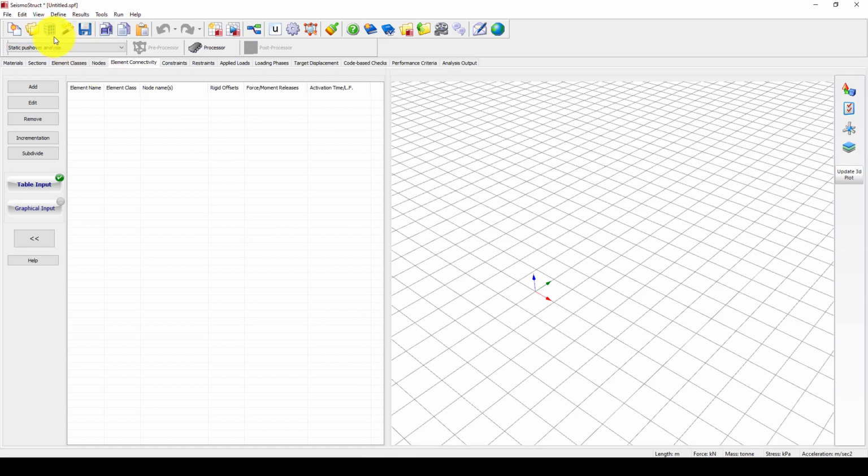So in the last part, you can go to the global response parameters, and you can check specific columns, beams, everything, and you can see the displacement and rotation in that column and beam, and you can print it. So let me go to one of them, let's go to node column. This one is called lower part and the upper part. I'm selecting these two and the rotational.